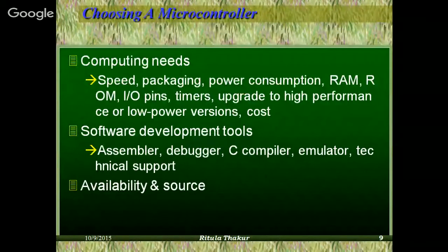Then amount of memory, of course, आपका कितना program का size बड़ा है, accordingly you will choose. Suppose you have a very small program, so you need not require very high amount of memory. Input output pins कितनी चाहिए? Input output pins का मतलब है कि how many peripherals you are externally adding to a microcontroller. Because input output pins mainly चाहिए होती है in case you want to have a real world interfacing with the